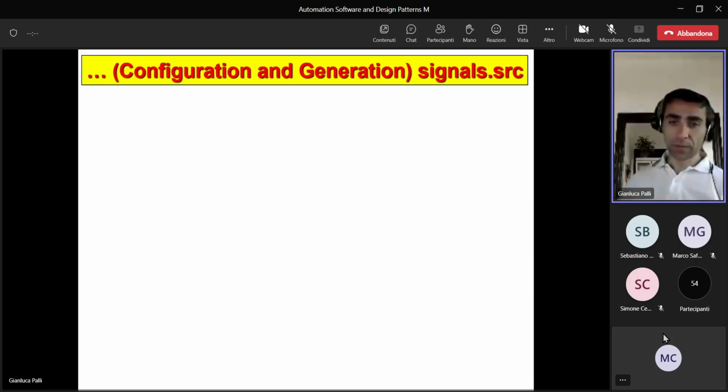If there's some protection device or emergency button that is activated or deactivated in case of protective devices, the safety PLC, that is another mechanism, and actually this mechanism is really simple and straightforward. It's made by very simple circuitry that just triggers the right inputs into the machine to stop everything as soon as possible, in a matter of microseconds.